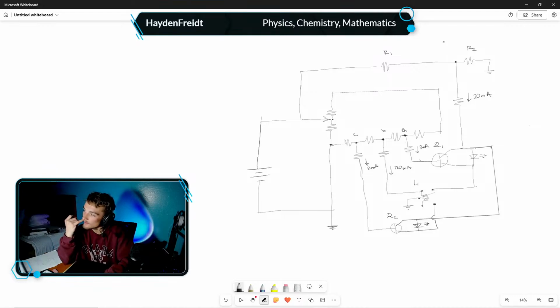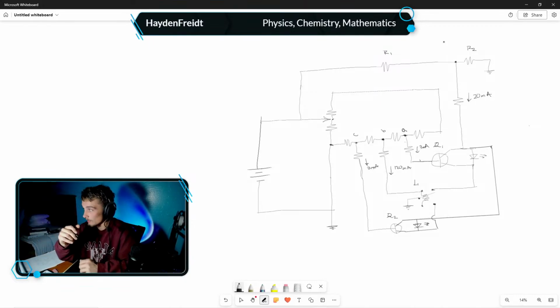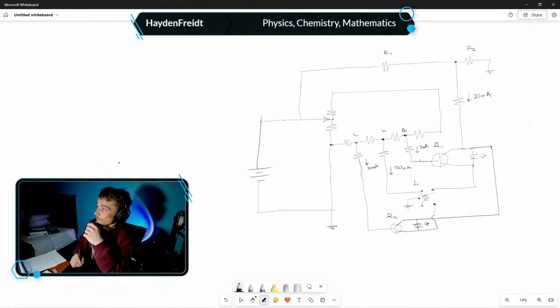we can go ahead and analyze that branch. Actually, let's just start with that. I guess this is my method of analysis. Watch and witness. This is how I'm gonna do it. Okay, so 100% need 5 volts across him. So 5 volts across him. We're just gonna draw it like this. Hopefully that's clean and you understand 5 volts. And so we have 9 volts total.